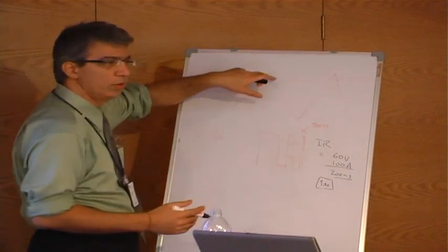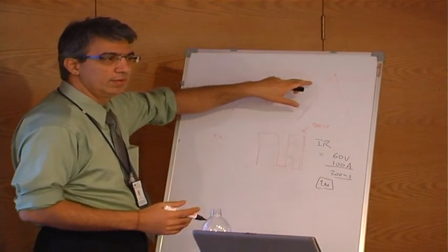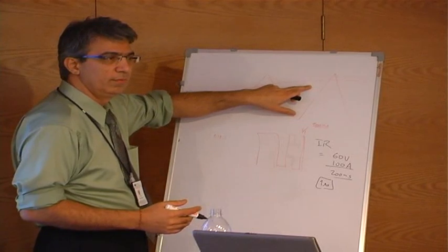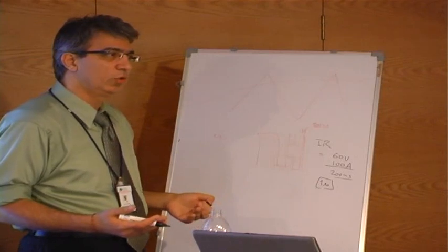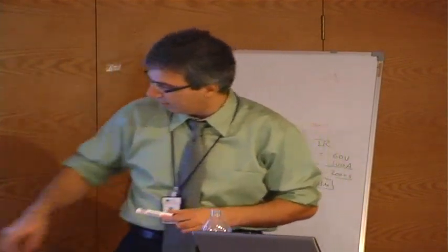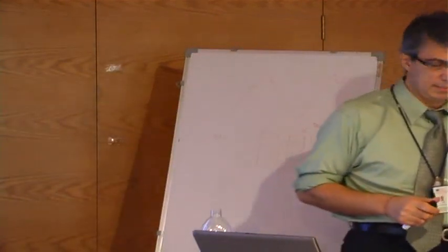So if you're switching at 20 kilohertz, that is 50 microseconds. Then 1 microsecond out of 50 microseconds is 2%. So you could set that: let me set it at 0.98 and 0.02. That's one way to think about it. So that's the thinking behind the limiter block. It's from having burned a few MOSFETs. So you're putting it at 0.01 to 0.99, so you don't want to go into overmodulation. That's right.